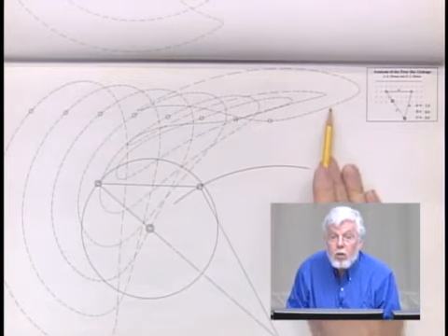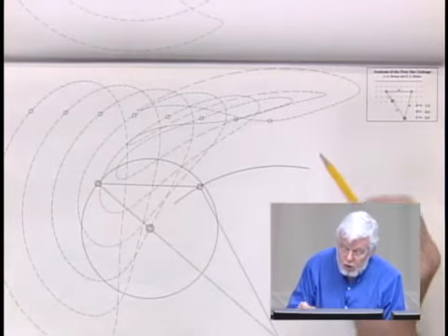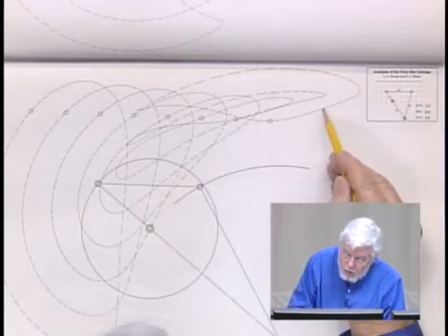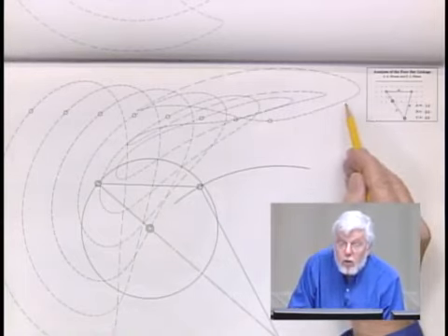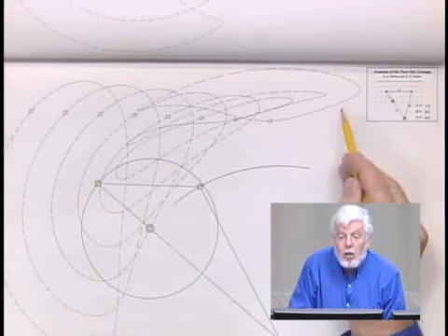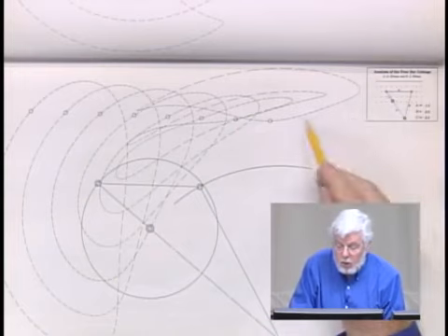That's the first thing that I notice. The second thing I notice is that during this portion of the curve down here, there's relatively little change in the lengths of those dashes. That indicates that I'm very nearly constant speed there. That's desirable. Remember I said at the outset that I wanted something approximating constant velocity to track my conveyor.